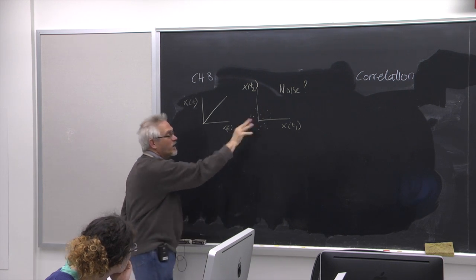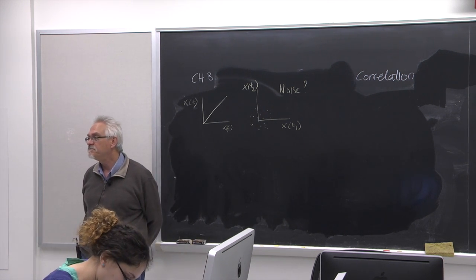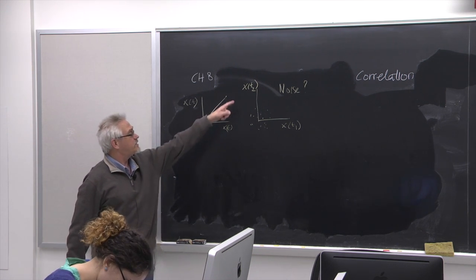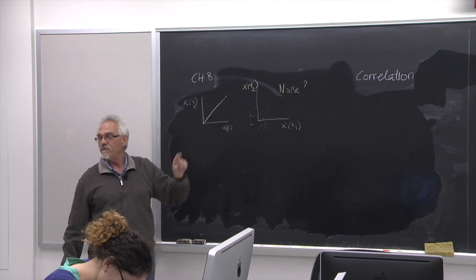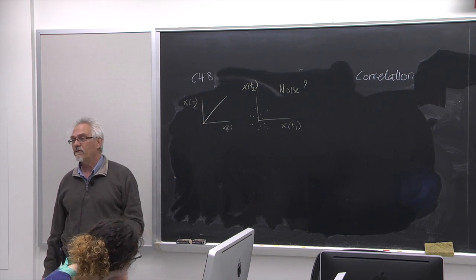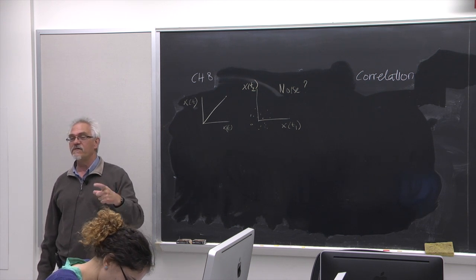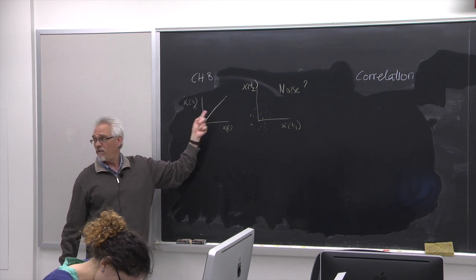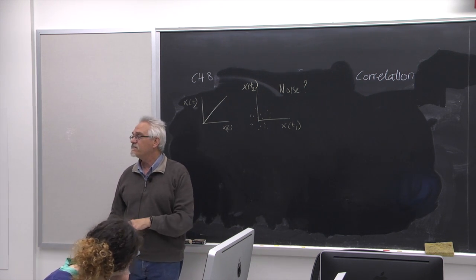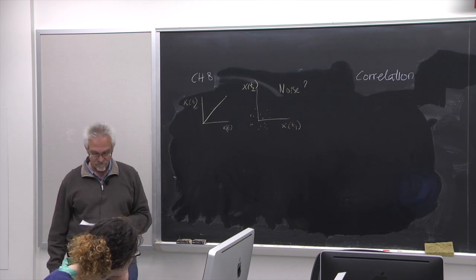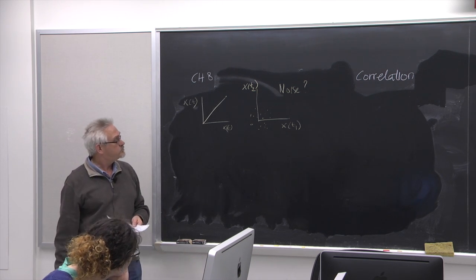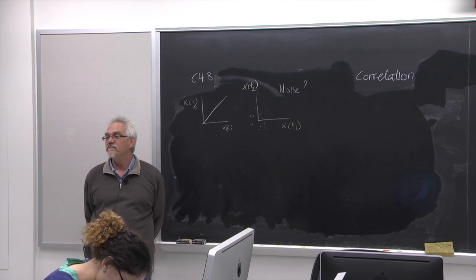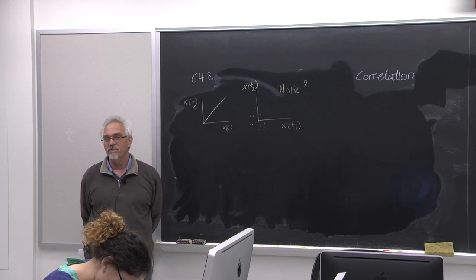It's all over the place, and on average, indeed, it will be 0. There won't be, unless, of course, T1 is T2. In that case, you will get that. So it's interesting that the autocorrelation function of noise is non-zero if T1 and T2 are equal, because then it will be 1. But it is 0 for all other cases. See? Do you have any idea what this would look like if it was a periodical system, periodical signal?